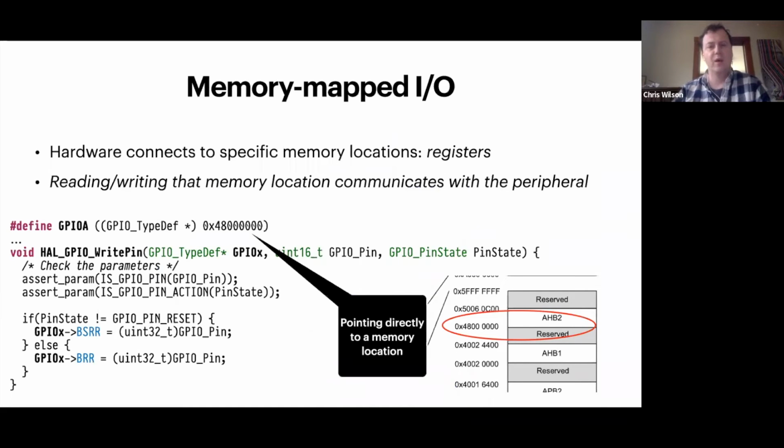And one of the defining characteristics, I think, of microcontrollers is this notion of memory mapped I/O, where there's a physical place in memory where if you write bytes into that, it will cause some behavior to happen on the chip. So if you write a 1 into this area in memory, then circuitry will convert that memory write into an actual, the pin will go from 0 volts to 5 volts.